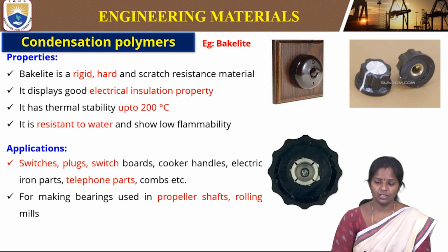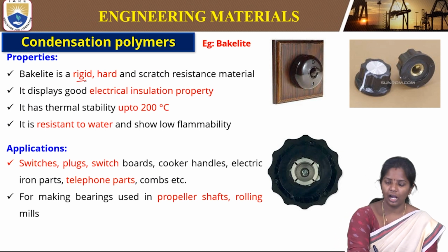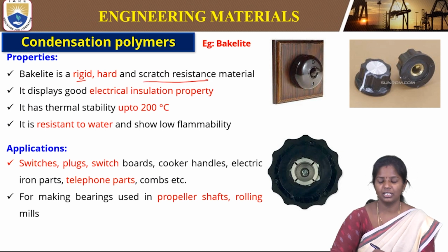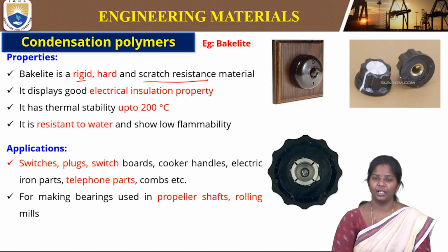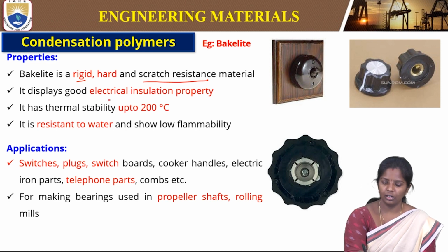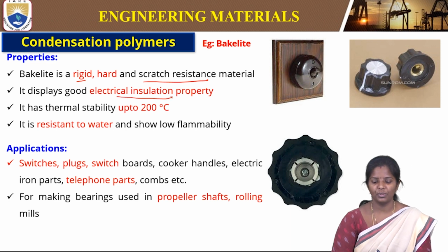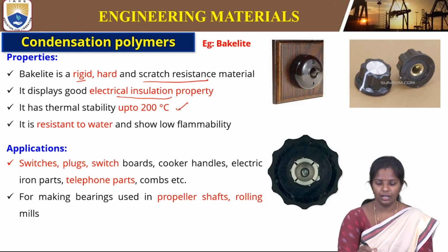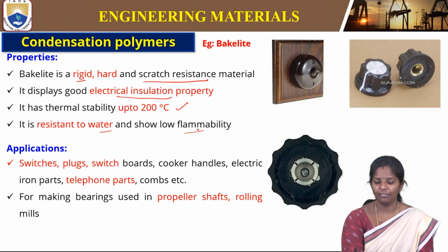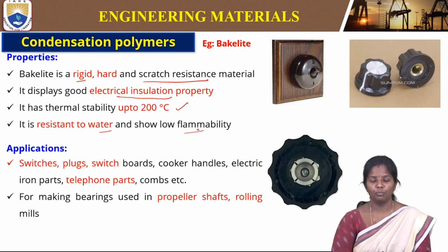So what are the properties of this bakelite? They are rigid, hard and scratch resistant material. Mostly because of this hardness, they are used for longer period applications. It also has good insulation properties, is thermally stable up to 200 degrees centigrade, resistant to water and has low flammability. So these are the good properties that bakelite possesses.